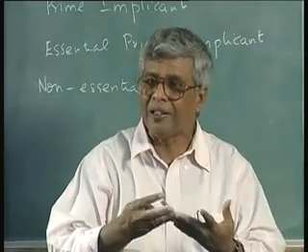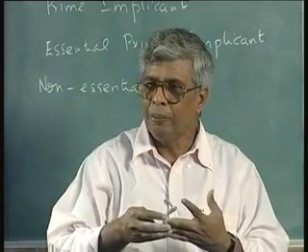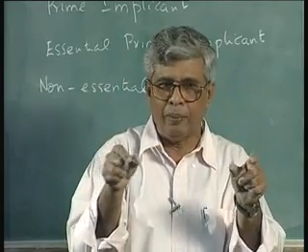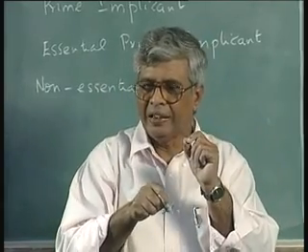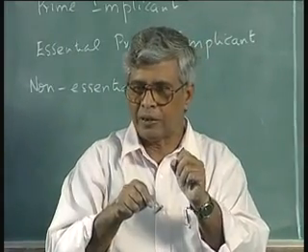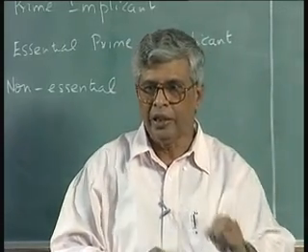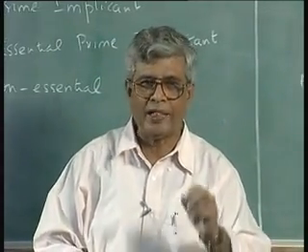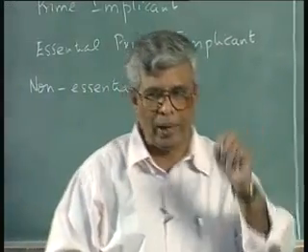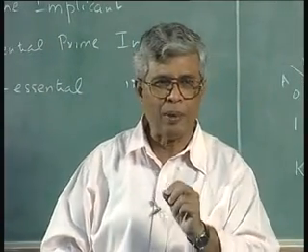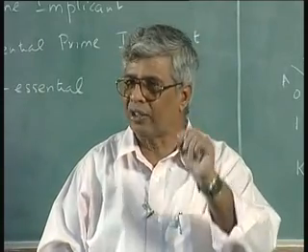That prime implicant is important, it has to be covered. But each of those two prime implicants, which I will get by combining this one in two different ways, are called non-essential prime implicants. So it's not necessary to include all non-essential prime implicants in the final output. It's only necessary to include as many non-essential prime implicants as required to cover all the ones in the map. Whereas essential prime implicants, all of them should be covered in your final output.